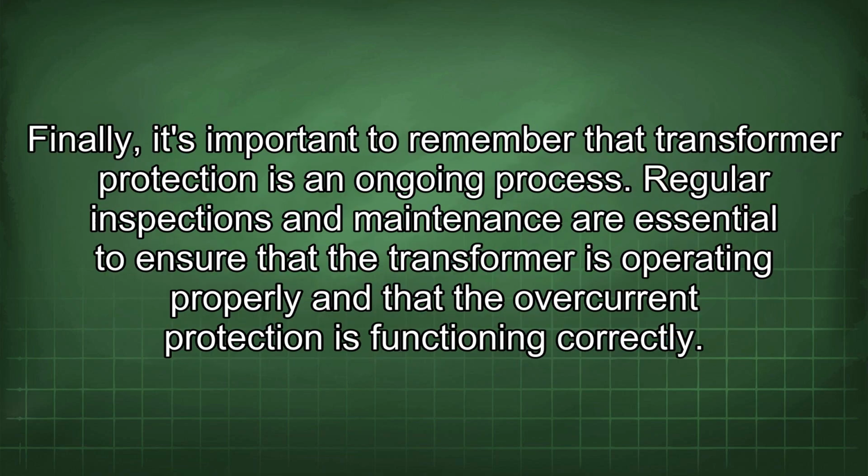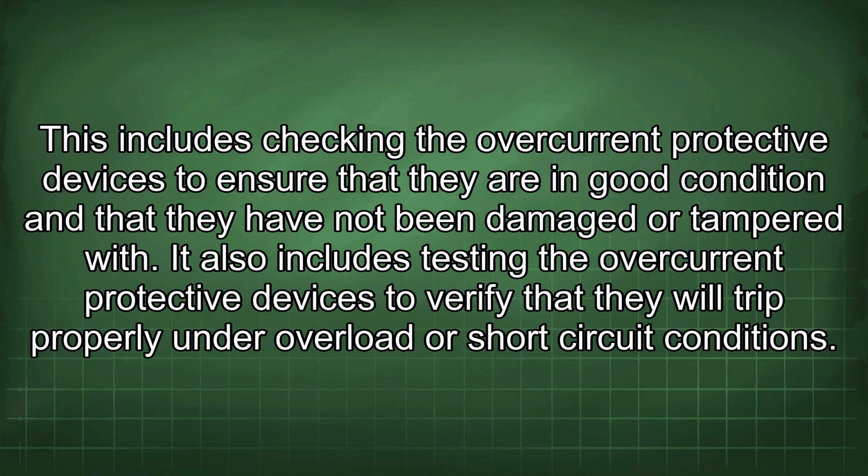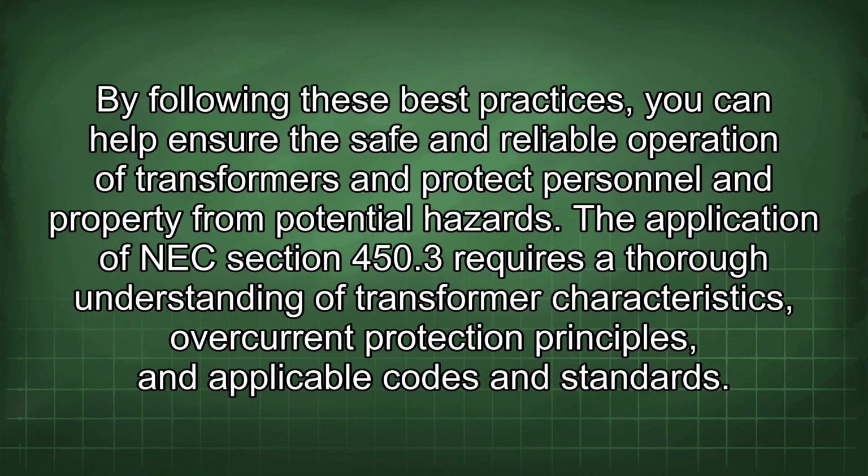Finally, it's important to remember that transformer protection is an ongoing process. Regular inspections and maintenance are essential to ensure that the transformer is operating properly and that the overcurrent protection is functioning correctly. This includes checking the overcurrent protective devices to ensure that they are in good condition and that they have not been damaged or tampered with. It also includes testing the overcurrent protective devices to verify that they will trip properly under overload or short circuit conditions. By following these best practices, you can help ensure the safe and reliable operation of transformers and protect personnel and property from potential hazards.